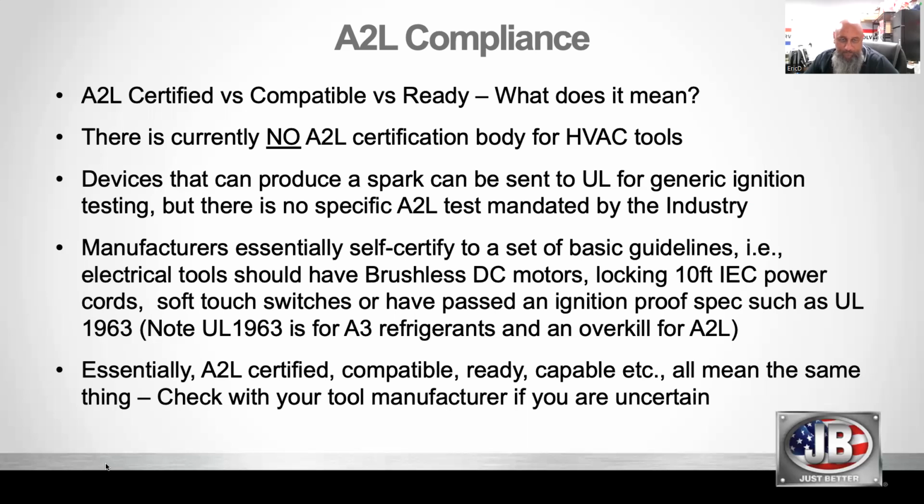So if you're meeting those guidelines, most manufacturers out there are self-certifying. We're taking the approach that for something like recovery, which is the most important one because you are actually touching the refrigerant, we've gone one step further. We are certified with UL for ignition, and we can go all the way up and recover propane. But on the pumps and all the rest of it, it's a self-certification process.